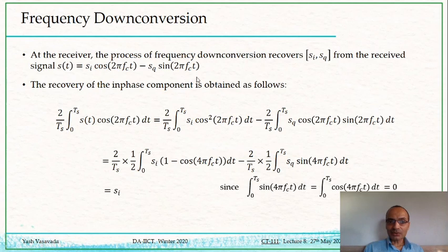And so this sine, I'm going to call it quadrature signal. This cosine, I'm going to call it in phase signal. And therefore, I will draw these two as two mutually perpendicular axes. That forms our two-dimensional IQ plane on which we drew the constellation points.